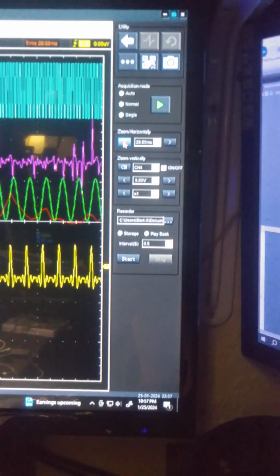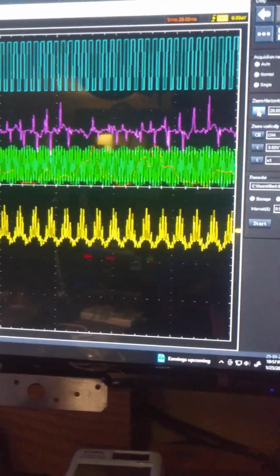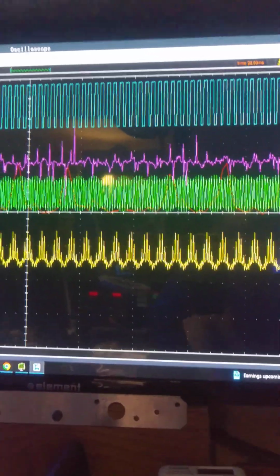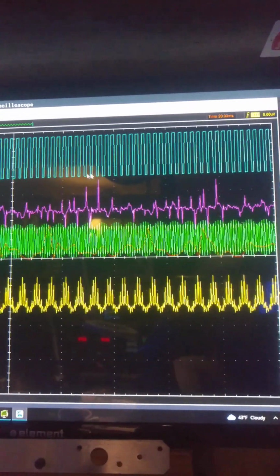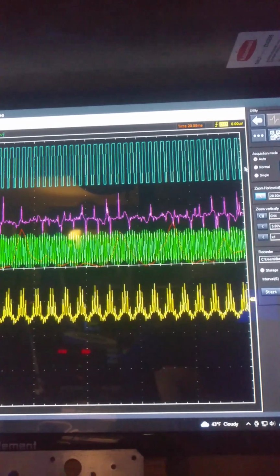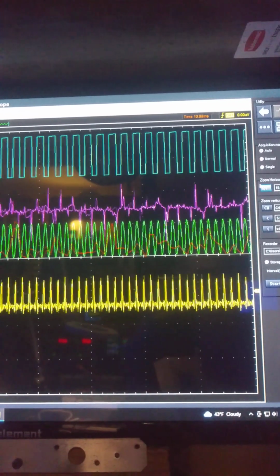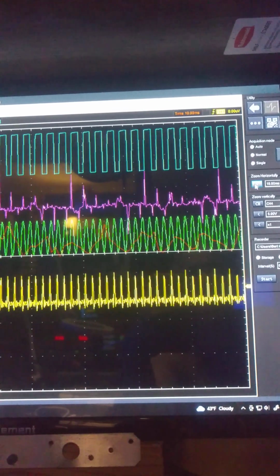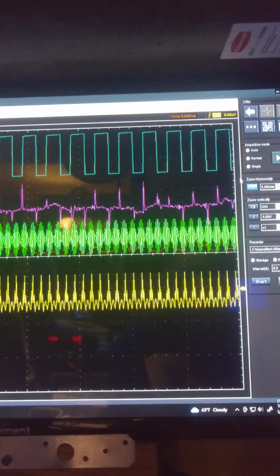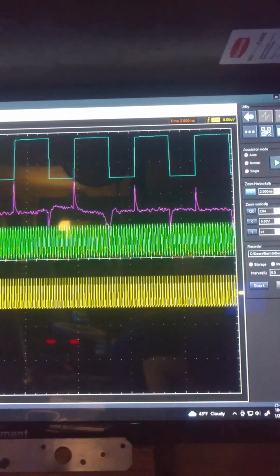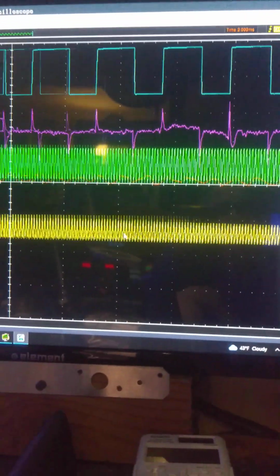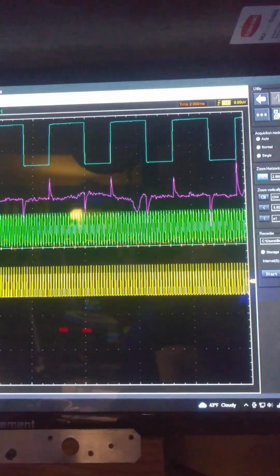Now let's do 50, 20, and say at 20, you start losing your characteristic. But this is actually starting to show signs of being the 400 hertz signal it is. And you can start telling that because as you decrease the range, if you see the pulse start to get wider and wider, then you're seeing the real signal. So that square wave, we know we're seeing the actual square wave, but look what these other things are doing. They're just going nuts.